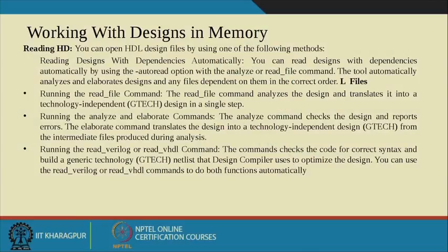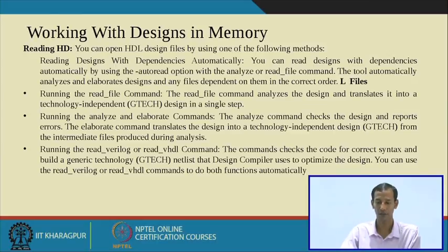Then you have to run the analyze and elaborate commands. The analyze command checks the design and reports errors, and the elaborate command translates the design into a technology independent design, that is GTech, from the intermediate files produced during analysis. Running the read_verilog or read_vhdl commands checks the code for correct syntax and builds a generic technology library netlist in the Design Compiler environment. You can also use read_verilog or read_vhdl to do both functions automatically.